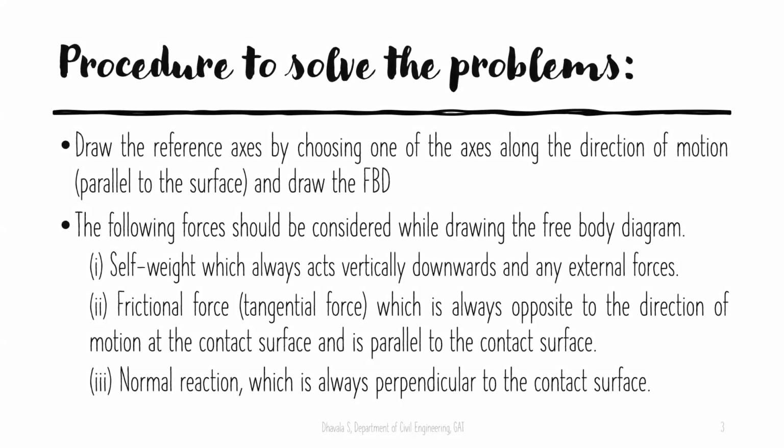Now, how do we solve the problems? In order to solve problems in friction, firstly, choose a reference axis. It is always preferred to choose the reference axis parallel to the contact surface. And after choosing the reference axis, we are supposed to draw a free body diagram, shortly called FBD. How do we write a free body diagram?